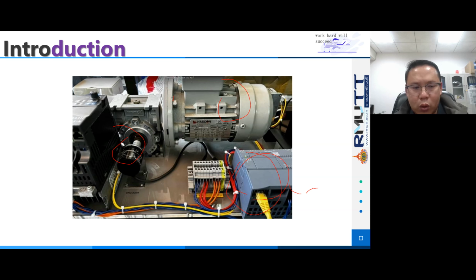When the desired motor position is set, the encoder or feedback sensor reads the current motor position. This data is sent back to the PLC. The PLC program calculates the error. The error equals the set point minus the measured value. If the set point is 90 degrees and the motor's current position is 70 degrees, the error is 20 degrees.